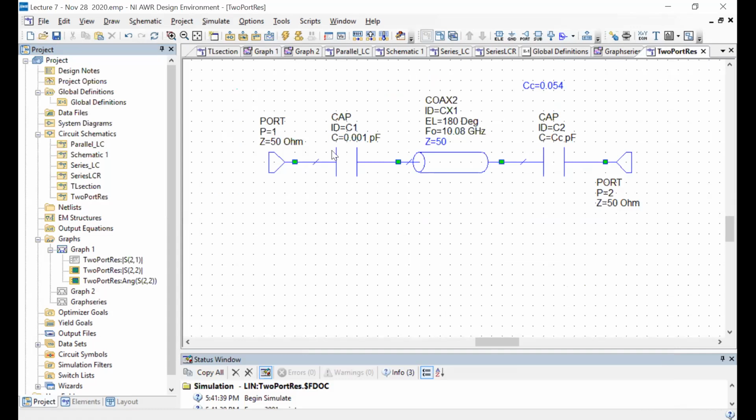So highly asymmetric 2-port resonators like this are effectively a single port resonator from the side which is strongly coupled. Okay, this is the strong coupling, and this is the weak coupling. And the presence of the second port is a purely practical thing, that sometimes it is easier to inject power from this side and just look at the output coming from the other side.